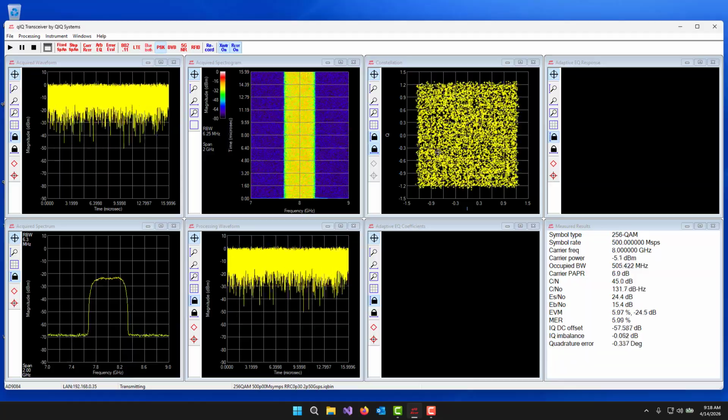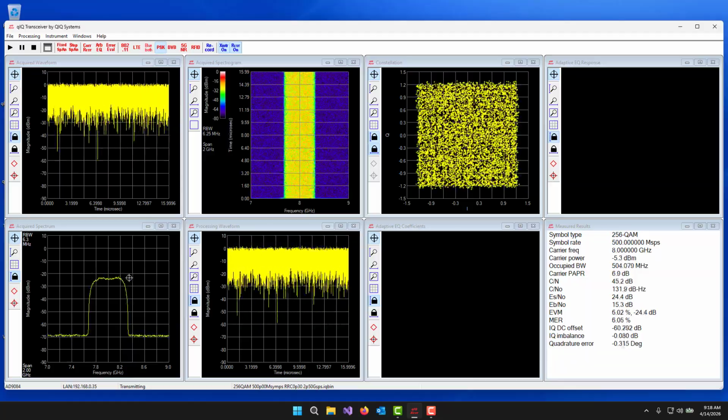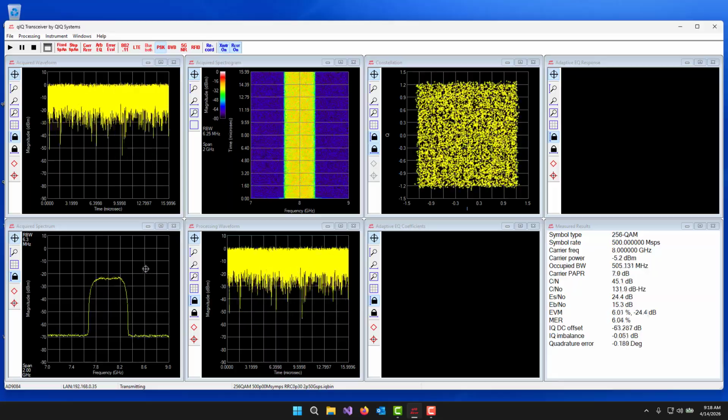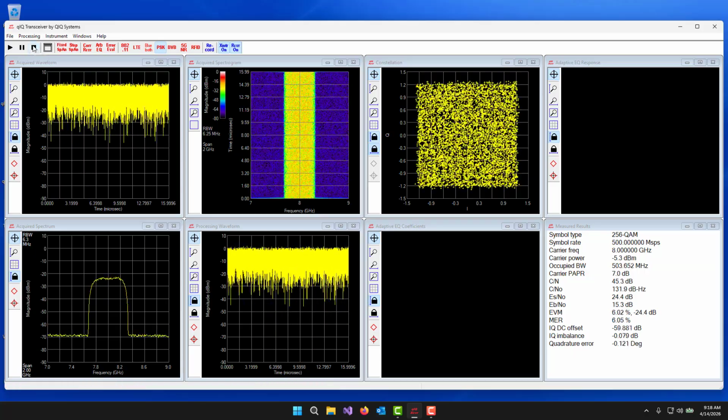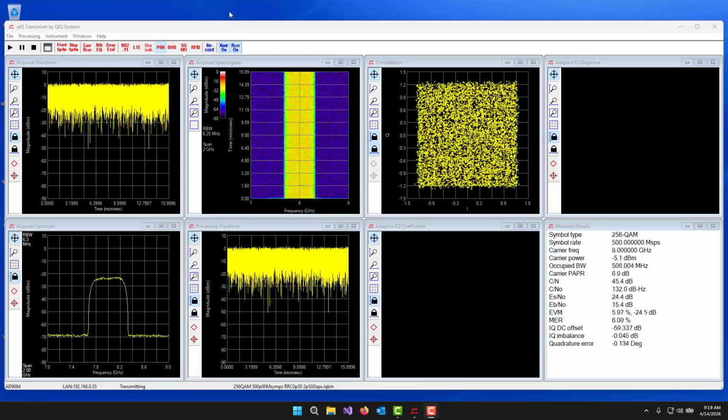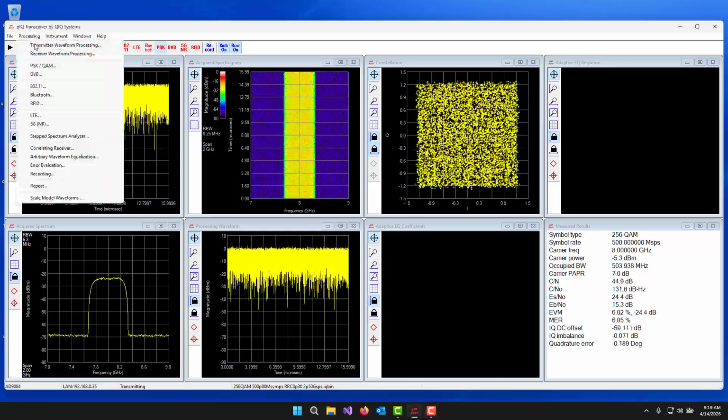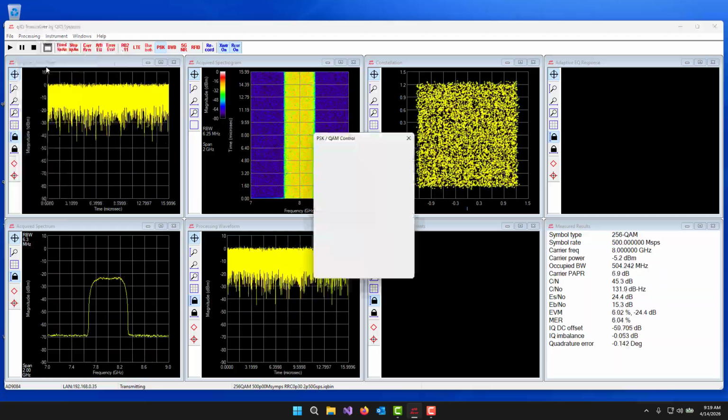That doesn't look very good. I can see a fair amount of ripple across the band here. So we do have the amplifier that's helping us with signal level, but we're having a rough time recovering this signal. Let's go in and see if our adaptive equalizer can help us here. Maybe it can clean up things.